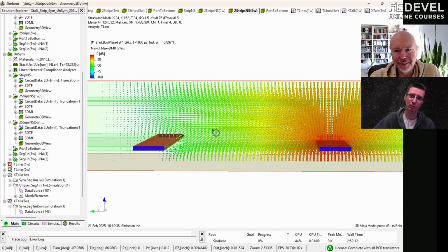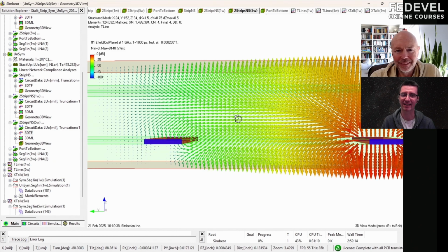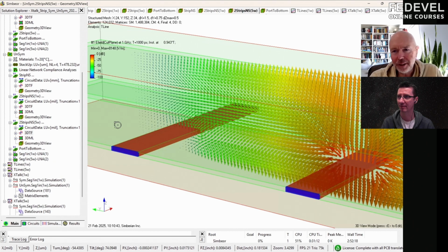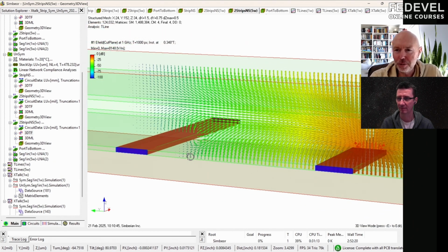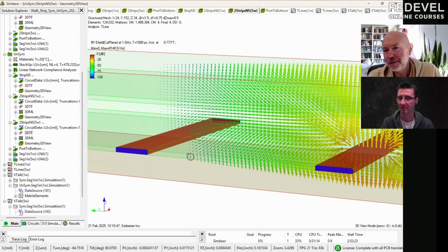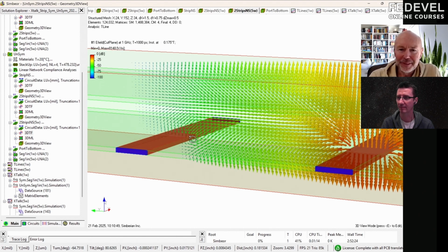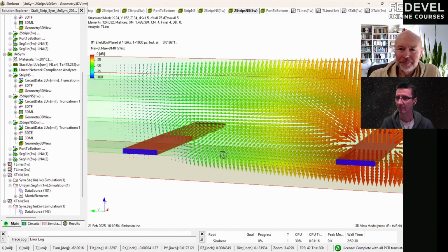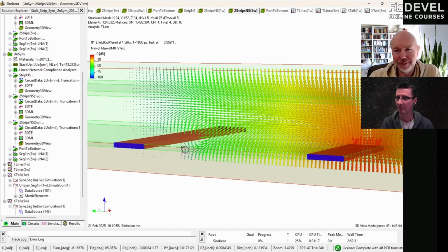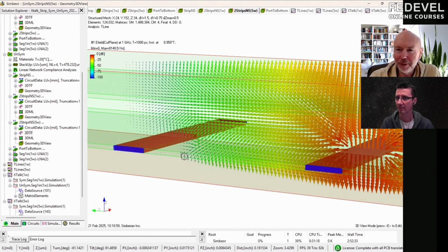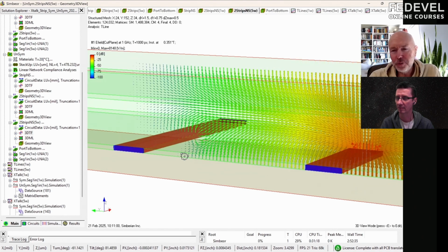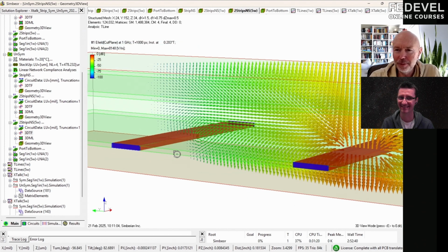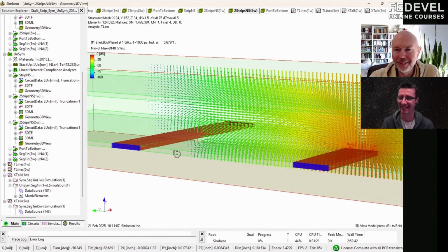Yeah, but we don't want to use different scales between different examples, because then it can be misleading. Right here we're using a -100 dB scale to see the crosstalk at the level of -60, -70 dB. But that's the beauty of a numerical experiment, actually. You don't have to go and buy much more sensitive equipment. You just add a couple of zeros, and here we go.